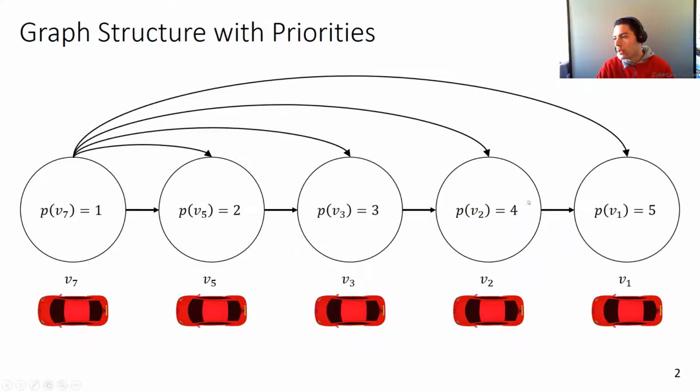And we use this communication link to ensure the constraint of a minimum distance of 0.3 meter. And we use this communication link to be able to follow the leader with a proper reference. So this will be 1, 2, 3, 4 times 1.5 meter, which means this vehicle gets a reference of 2 meters behind the leader vehicle. Does that answer your question?